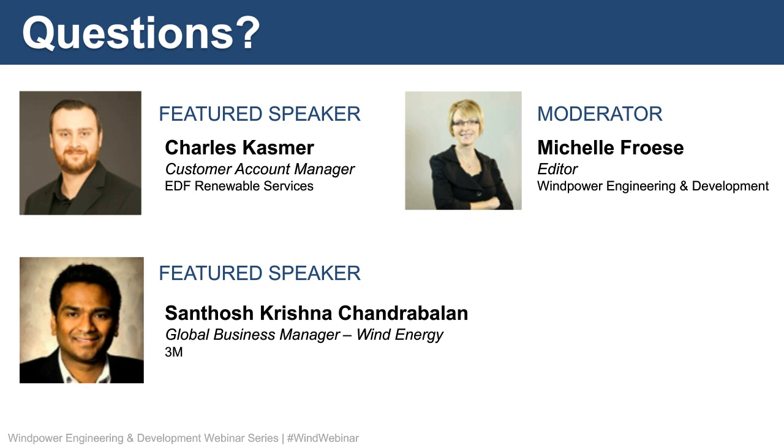Thank you, Santosh. I've got one last question for you. I imagine this varies, but how long do VGs tend to last over time? And have you experienced any major failures? That's a great question, and that's the $1 million question, right? How long anything lasts overall. We now have vortex generators with this technology installed for more than 4 to 5 years. The only failures we have seen are from severe icing or lightning strike. Other than that, we have never seen a vortex generator fail. So with that said, a minimum of 5 years should be very possible.